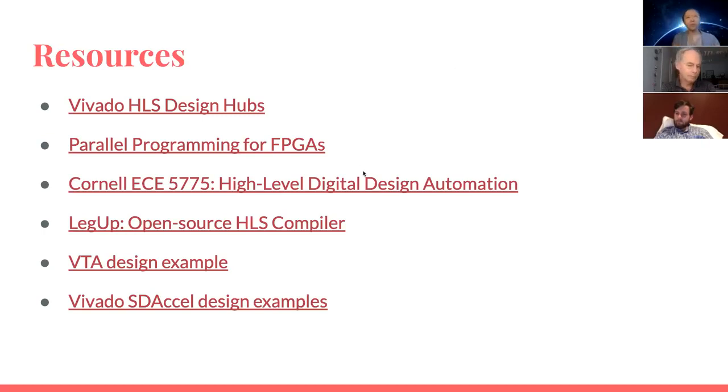But in order to optimize these designs, you really need to look into the Vivado design examples to see how they add the pragmas, because the plain C abstraction wouldn't be enough for you to specify a high-performance accelerator. Other than that, you can also look at some structural high-level synthesis designs, where you specify your design in SystemC, a language that allows you to specify parallelism in your design through channels. It has explicit parallelism and multi-threading models in C, so sometimes a lot of ASIC designs are designed using SystemC, because you specify the design structurally in a very fine-grained, explicit way.